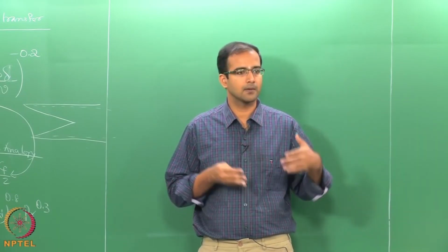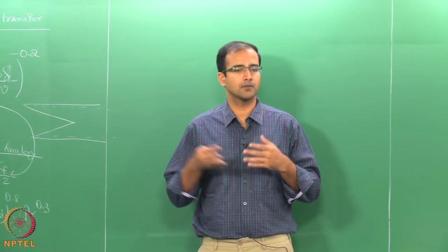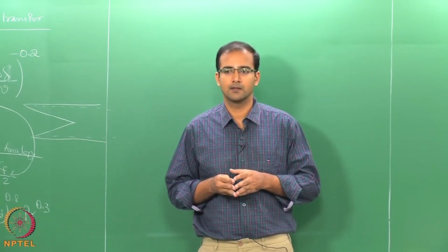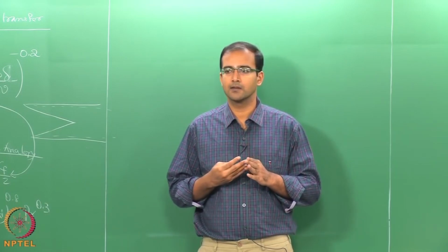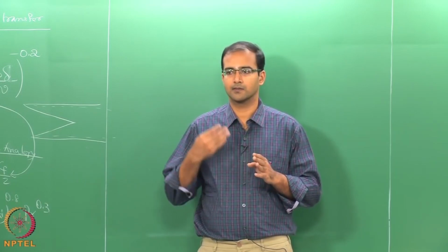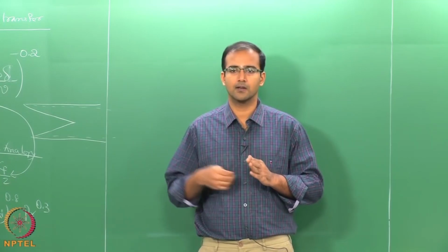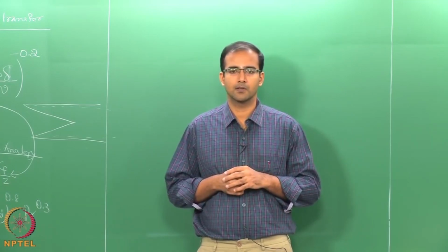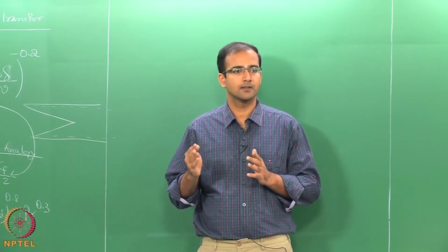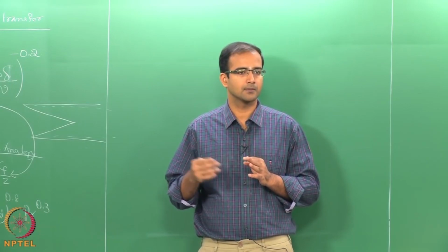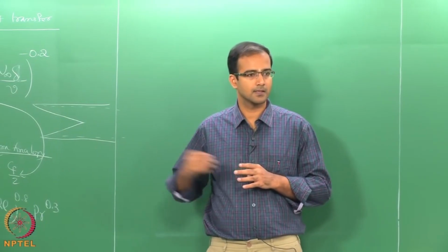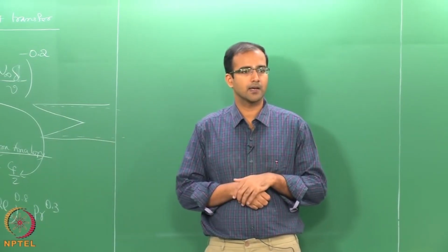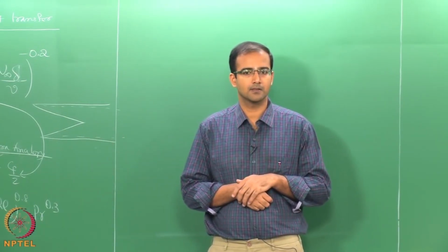Whatever Reynolds number may be, once the two boundary layers are merged, you will have the same profiles, and the only thing that will decide the Nusselt number will be the boundary condition, whether it is a constant wall temperature or constant heat flux. Only that alters the nature of the temperature profile, whereas in the turbulent case, this is still dictated by the Reynolds and Prandtl numbers.